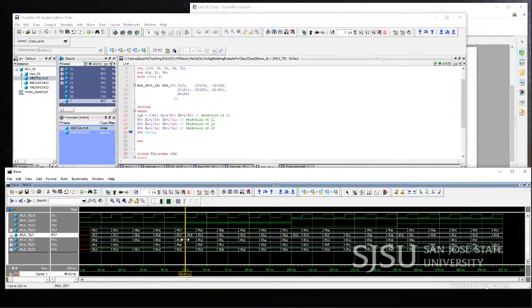They're exactly matching, except at the point when the selection becomes 0 and 1. Now it starts selecting I1, right? 4 hex 5, 5, 2, C. Now it is following whatever value is on I1. And then it was happy till 100 nanoseconds. And then suddenly, boom, it starts following I2 because my selection becomes S1 1 and S0 0.